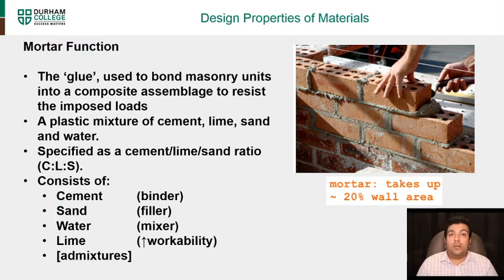Then we add other admixtures based on the requirements, but the CLS are the most common ones. You will find there are different ratios used in different parts of the world. Also, another interesting thing is mortar takes up about 20% of the wall area. So if you have a wall area, you can almost say that mortar takes up about 20% of that wall area.